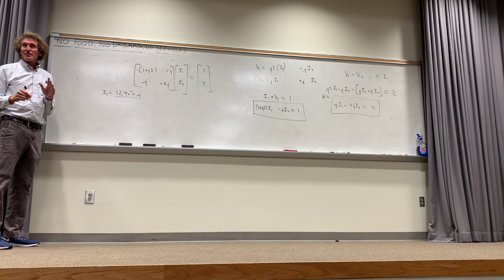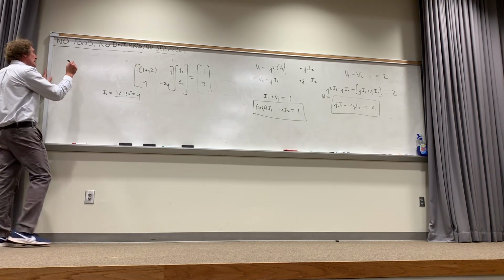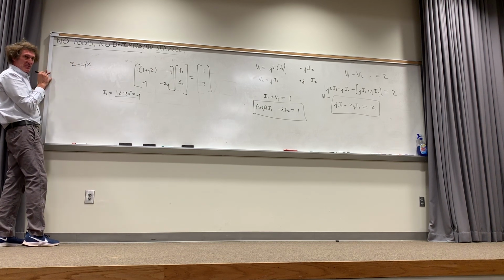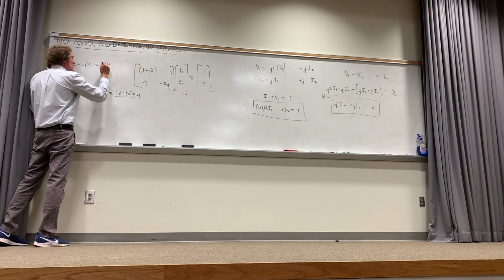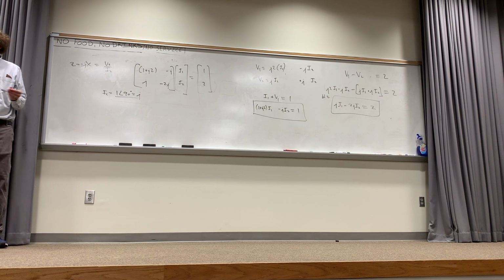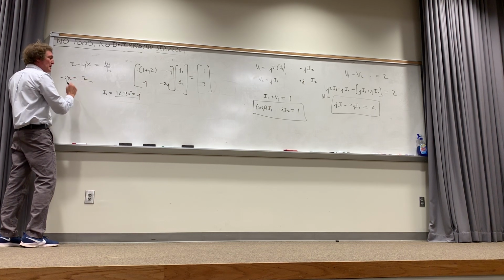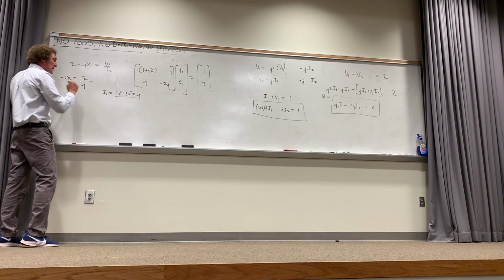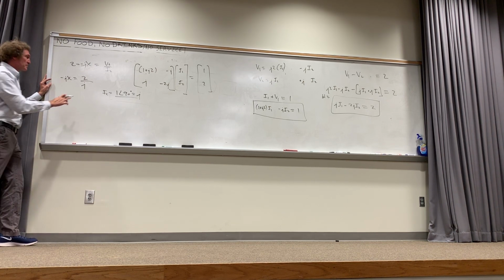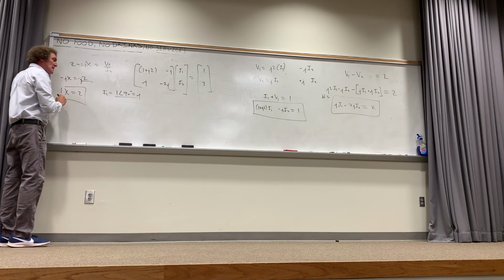Now, they want the value of that impedance, JX, right? So the impedance of the output was just JX. And what is that, or minus JX, pardon me, right? And what is that? Well, that's V out over I2, isn't it? You with me? What is V out? 2 volts. So this minus JX is 2 volts over I2, which is just J, correct? Do you see that? Take 1 over J, you get minus J, don't you, class? That means X equals 2. I believe that's his answer.